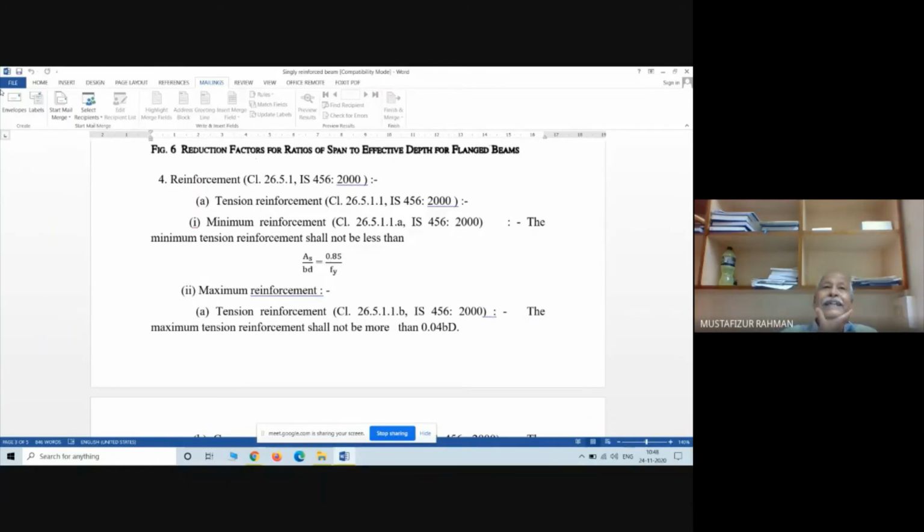One condition was that at least one reinforcement bar should be available at each corner. Since if our beam is rectangular, then at the 4 corners there is reinforcement. Now it is simply supported, so it is sagging, and tension is going to occur at the bottom. So this is one condition, from the construction point of view.